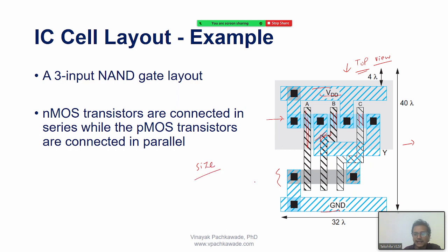Let's say this was your assignment to design a chip physical layout for this 3-input NAND gate. How do you come to what was the size of the total NAND gate that I drew? How will you estimate that roughly? For instance, you just know the information about technology library, 10 nanometer, and you know the lambda rule, right? Lambda rule is L by 2. So you know the layout technology rules.